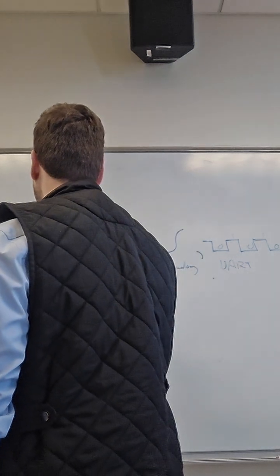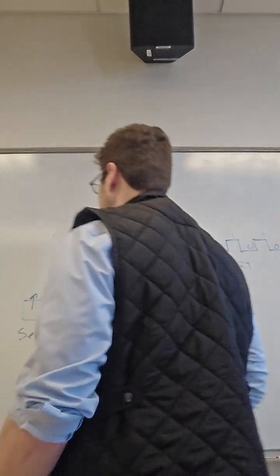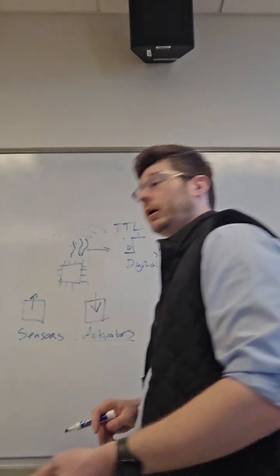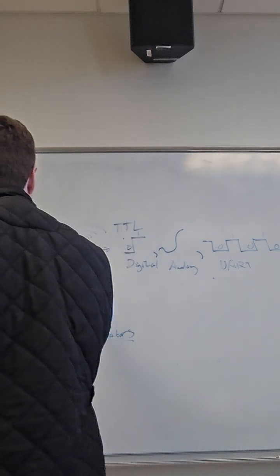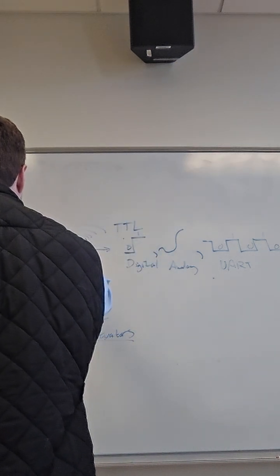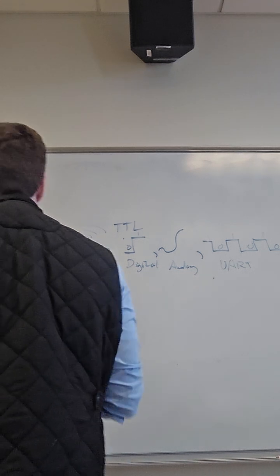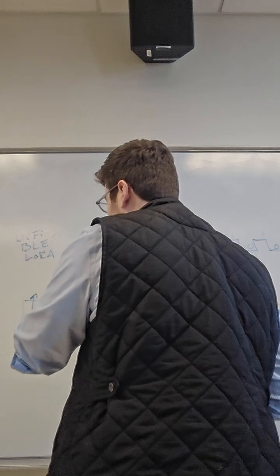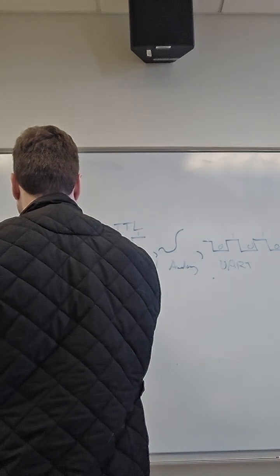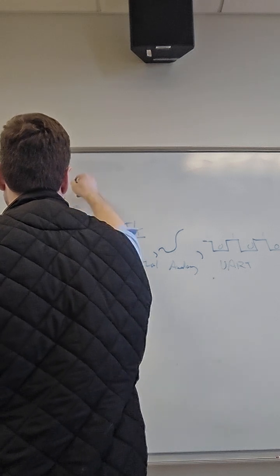So we do that with a gateway. So we have either wired, so we would do Ethernet, TCP/IP, or we would do wireless, which would be Wi-Fi, or Bluetooth sometimes, or LoRa sometimes. I keep saying that, I'll get into that in a little bit. But essentially a radio signal that carries that information out and is received by a gateway.